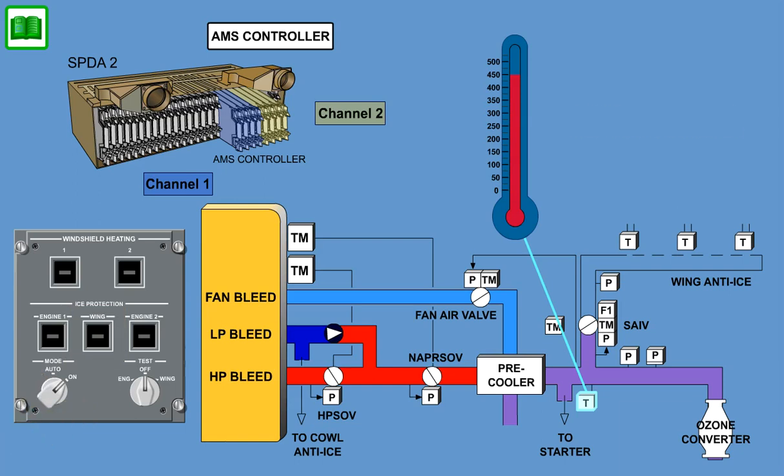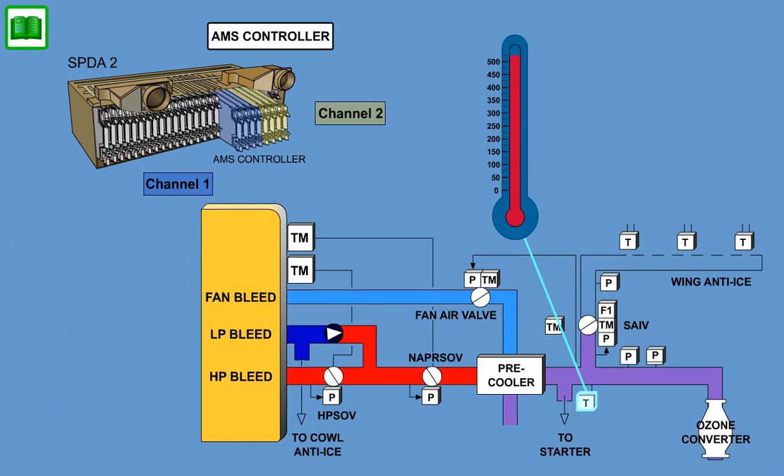If temperature rises above 450 degrees Fahrenheit, 232 Celsius, for more than 2 minutes, or greater than 500 degrees Fahrenheit, 260 Celsius, for more than 10 seconds, the affected system will shut down.